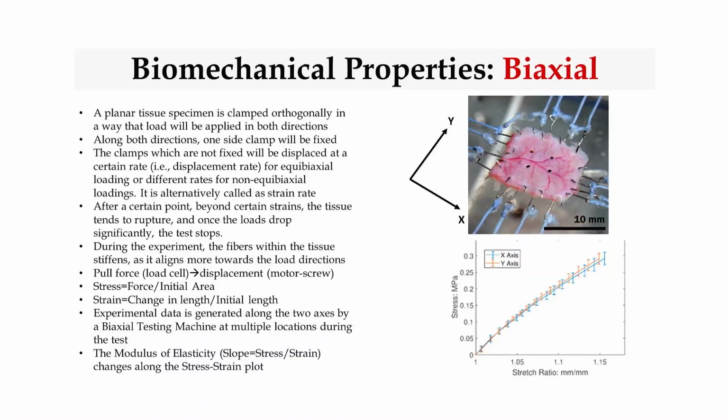Stretch ratio, why do we introduce this term? Because this is often used interchangeably for a lot of different mathematics which goes along with the understanding of the mechanical responses of the soft tissue. So I'm going to explain about stretch ratio later in the classes, right? But let us just assume it's strain plus 1. The entire plot is being shifted by the number 1, right? Yeah, so stretch again is unitless, similar to strain. You're looking at the stress on the y-axis. Here you're looking at two plots.